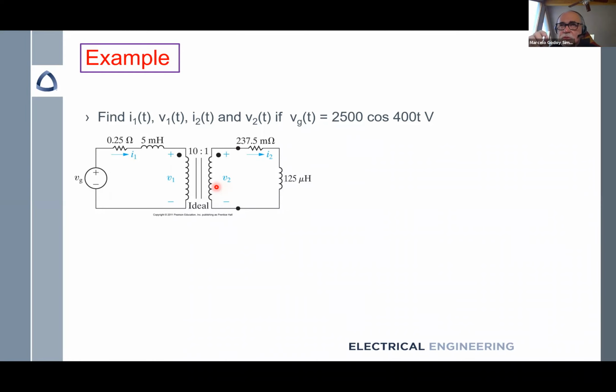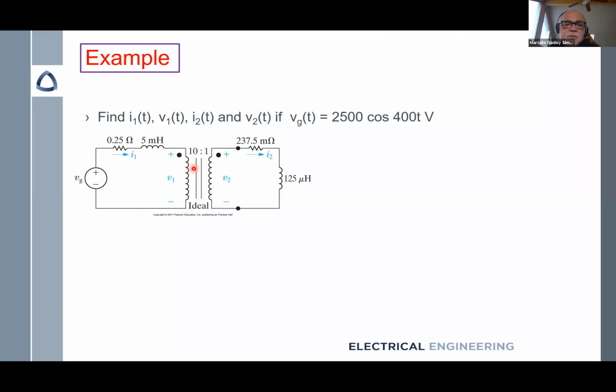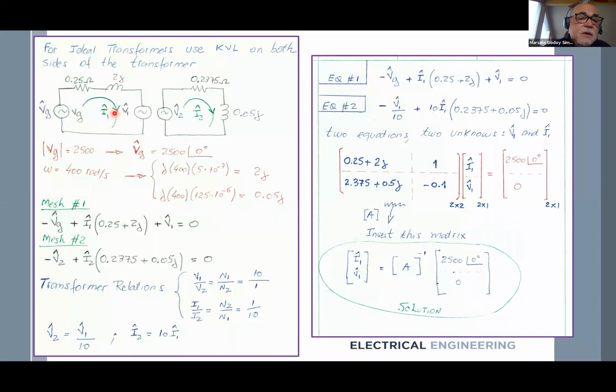So the first thing you do is write that, okay? And then use that formulation. I start from my transformer and I make a substitution here for the reactance. And then I assume that I have a voltage V1 here, V2 here, and then I write the expressions for the ideal transformer. Okay, let's go there.